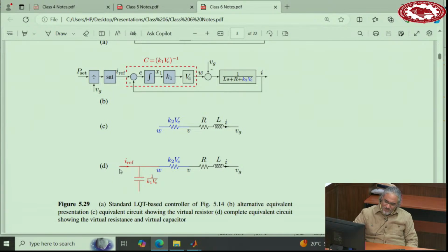So if you look at this system, and let's say something happens here in the grid, like what we said before. If this capacitor can respond properly to what happens here, it will give inertia, because a capacitor stores energy, like the rotor that is rotating and stores kinetic energy.